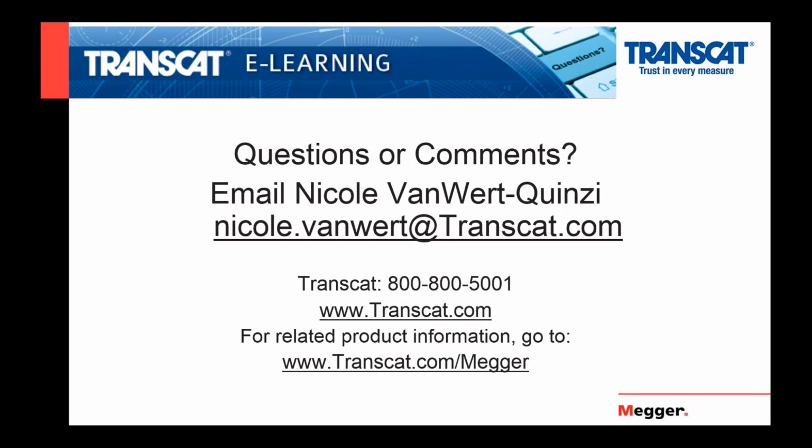Yeah, parallel strings are basically used when you have a critical application and you're using VRLA batteries, valve regulated lead acid batteries, because they can fail in an open mode. If you use a series string with them and you get a failure, you may not be able to get current through. So when they're needed, they may not be there. This is why you want to use them in a parallel mode, because if one fails, you can still get current through the parallel string. So whenever you have a critical application and are using VRLA batteries, you want to use parallel strings. Otherwise, you can use vented lead acid, VLA batteries, and use a series string with them. Those are flooded batteries, obviously.